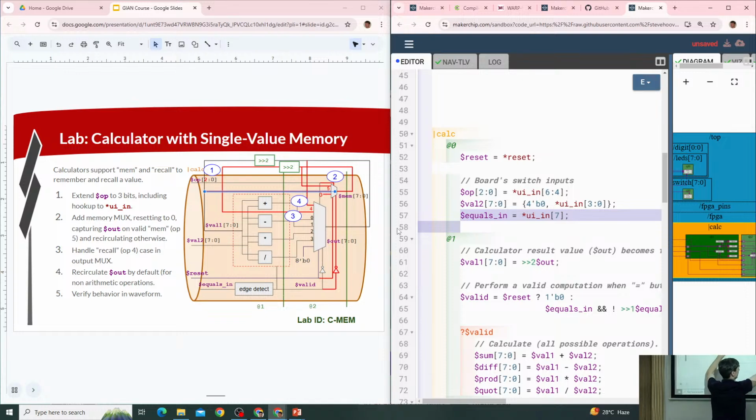The reset operations are marching through, clearing things out. The one behind it is marching along, doing something real. So reset's going to be held for a large number of cycles. The machine's going to stabilize. But if we just imagine that we're in some unknown state, and we just have 3 cycles of reset, right? We have those 3 reset transactions going through. We don't have the machine cleared out yet. It's in some random state deeper in the pipeline, but we march along, and we're cleaning up in front of ourselves so the valid transaction can come along.